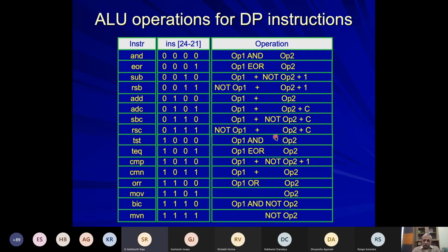All right, sir. So the multiplier, the block that does the multiplication, is it also called a coprocessor? Well, technically, whatever is there in a coprocessor could be directly included in the processor. It's a matter of how you want to partition. For example, in this version of ARM, there is no divide instruction. If you have to add a divide instruction, it has to be beyond that.